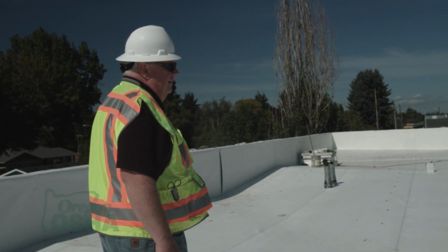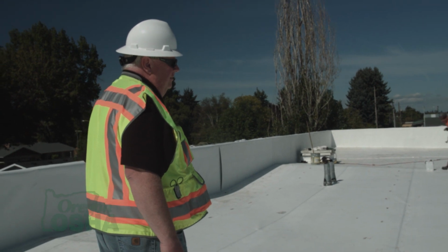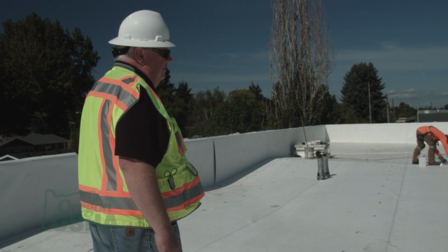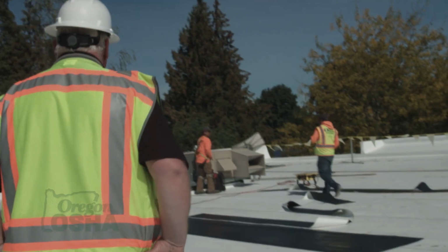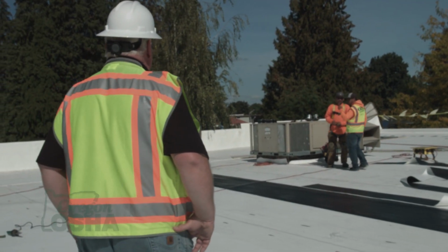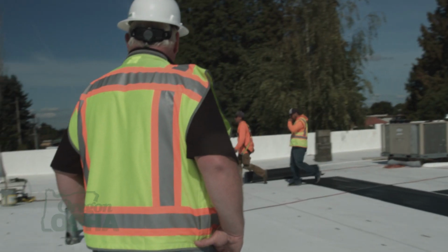You can't just have a huge area and have the safety monitor walking along. Now, the safety monitor cannot have any tools in his hand, can't be carrying any equipment. We typically have our safety monitor wear a different colored vest so that they stand out. The policy for our company is we have one safety monitor to 2 workers. And that safety monitor doesn't do anything except watch those 2 employees work. They have to be within shouting distance, and they have to be eyesight. But again, that falls in that 50 by 50 area to work in.